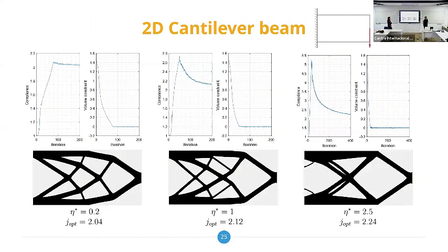But this is not, of course, an ideal thing, because we should include these additive manufacturing constraints. But as eta is increasing, you can see here we started with a lot of bars and we are converging into results. This simulation maybe is not completely converged, but these bars would disappear. You would obtain just 2 thicker reinforcing bars, so I would say with high beta.